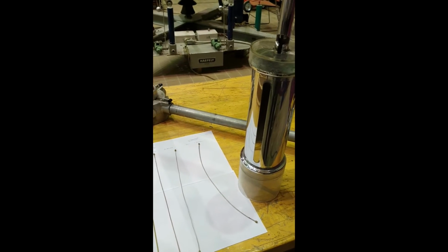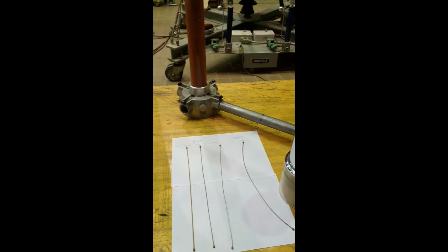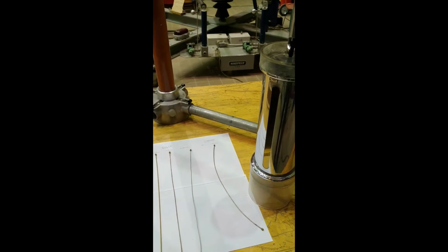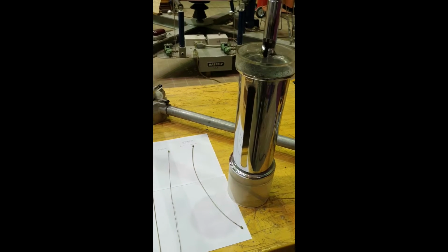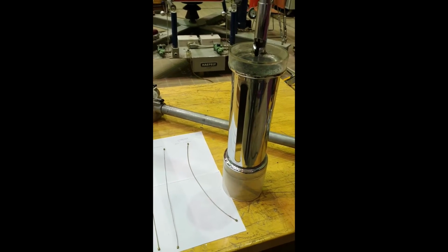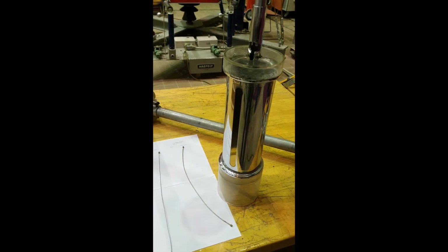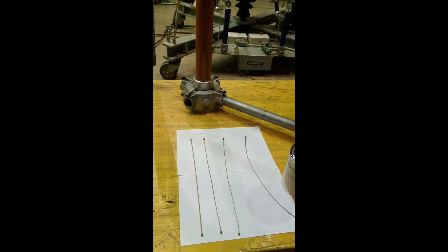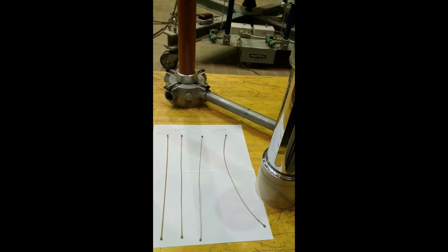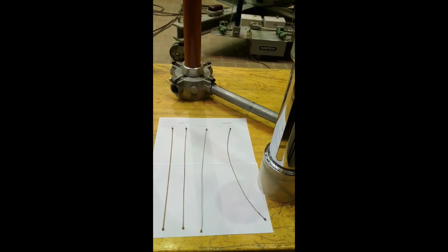The procedure will be the same: just change the conductor inside, then go to the DC source, apply the DC source, and increase the voltage until you find the onset voltage with the help of the radio. So our detection source will be the same, the radio. Let me show you how to insert this conductor inside the coaxial geometry.